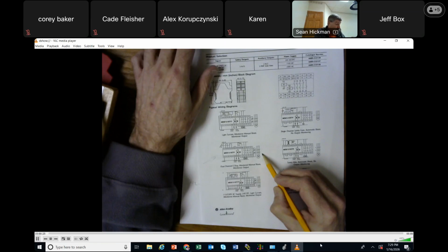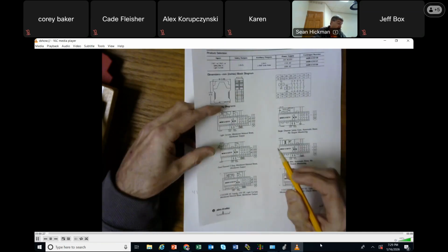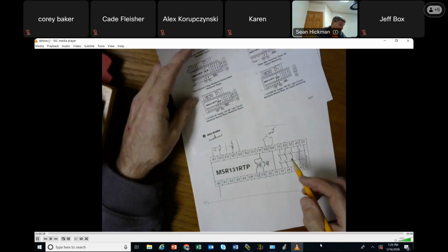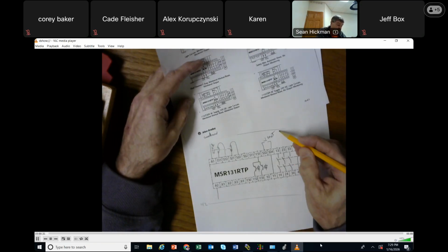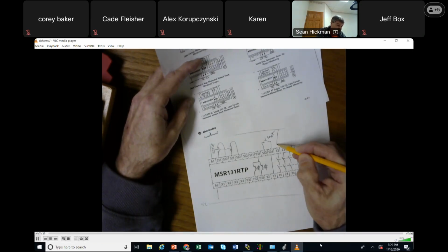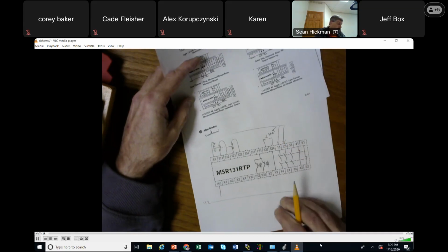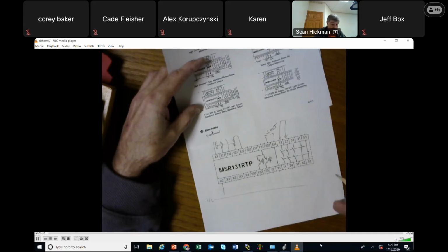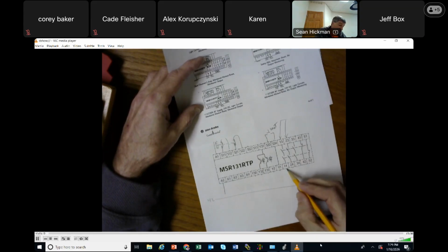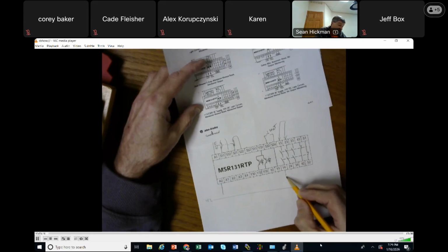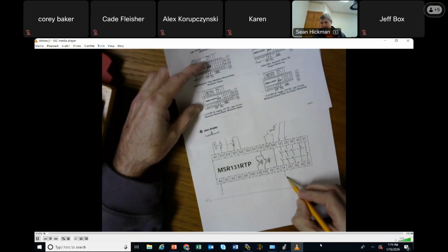So what we're doing is we want to turn on, and here's our load, 13 and 14 is going to, you know, we're passing power into 13 and 14. And in order to turn the motor on, we have to turn on the contactor. So I'll draw NEMA instead of IEC.